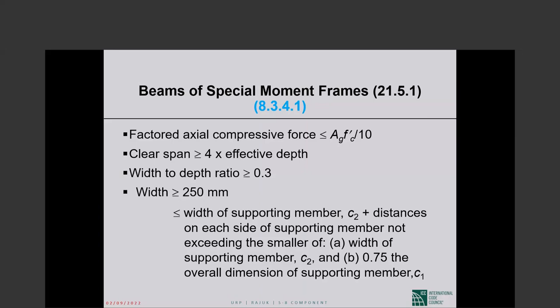So let us say you have 4 stories and 5 bays, and let us say at the top, in the middle bay, you don't have a beam. Then the frame you're designing as part of the seismic force resisting system will be minus that beam. And then you are okay. What you don't have, if you don't count on it, you are all right.